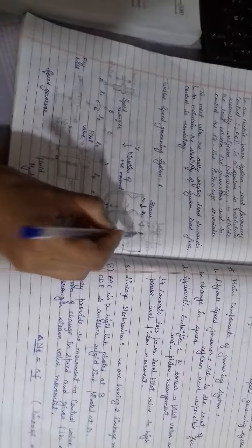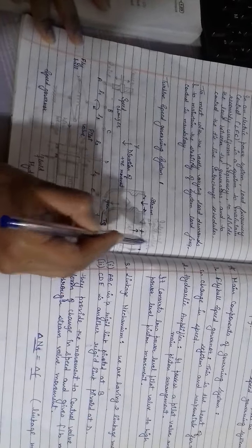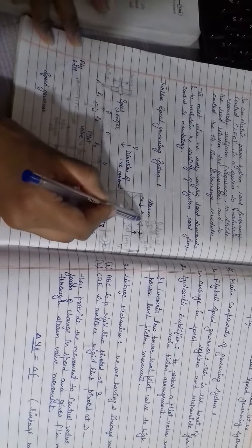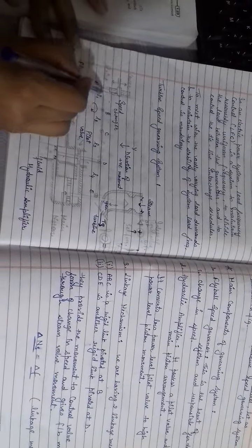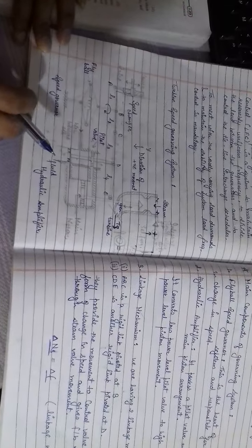It gives the generating frequency, and we have the set frequency. If there is a difference between the set frequency and the generating frequency, it gives the indication to the integral controller, which gives feedback to the speed changer, and the speed changer gives the indication to the flyball, and it controls the speed. By this we can understand the turbine speed governing system.